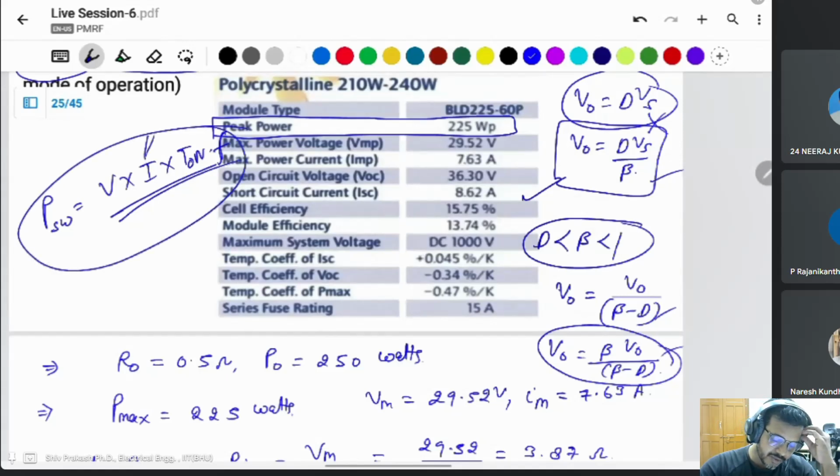But in discontinuous current it will be zero. That's why switching loss will be reduced in that condition. The power efficiency will improve in some conditions, but you need a high rating of inductor there. Then there are a lot of disadvantages, but voltage will be increased.